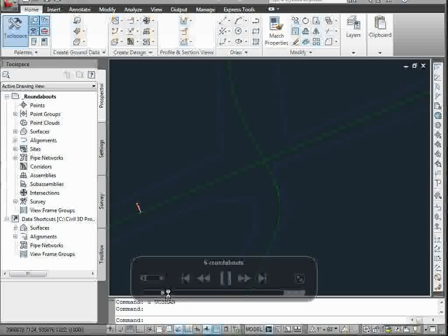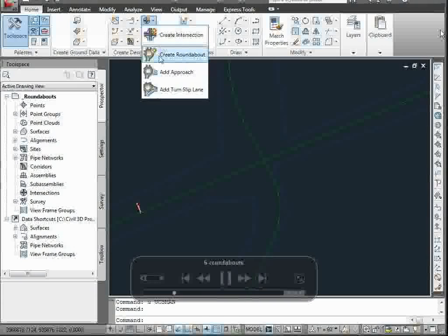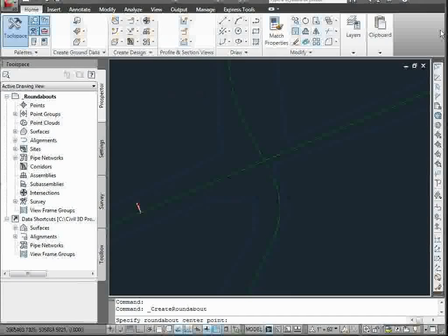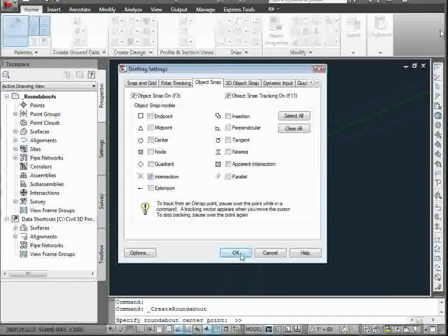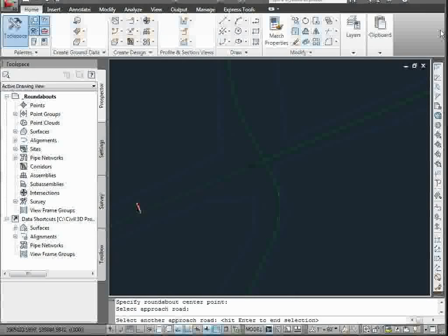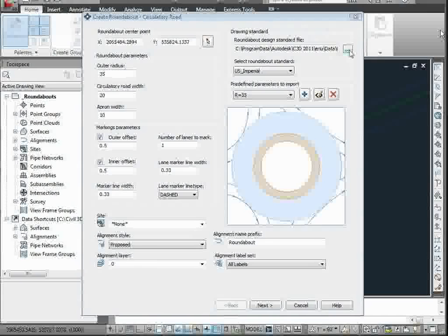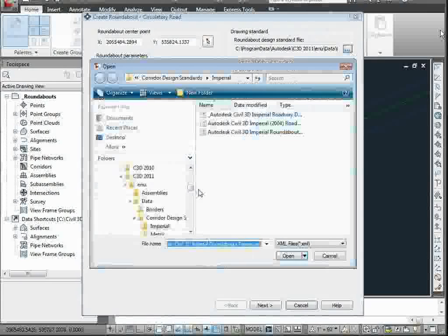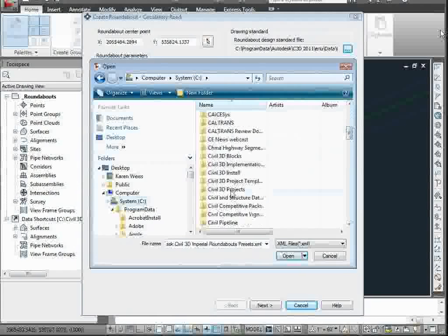Civil 3D lets you take this data and come in here and compute a what-if scenario, which is what we want to do. So we've got these in here, and what we're going to do now is see if a classical roundabout would work. We'll set our standard CAD settings, and grab each of the corridors or each of the geometries that come in. And as it does this, you'll see a little dialog that pops up for roundabouts. This is built in Civil 3D.